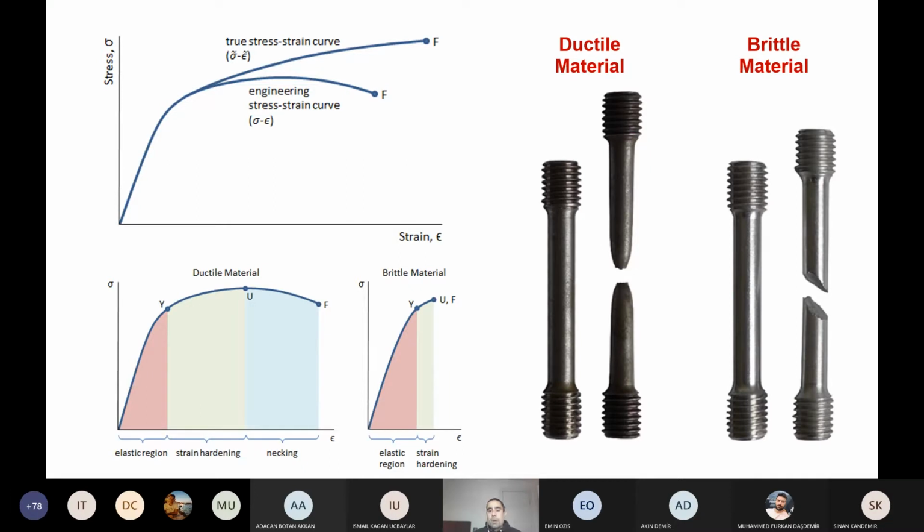However, with brittle materials, we can barely change the shape. It will just deform a little bit, and then it will fracture or rupture all of a sudden, like glass, which is a quite popular brittle material. If you look at aluminium, for instance, which is quite ductile, it takes some time and deformation until you can break it. So these two terms are extremely important for us. Ductility comes into play when we talk about materials that we are going to form and produce parts with, and brittle materials are mainly a subject of the tools which we use to form the parts.